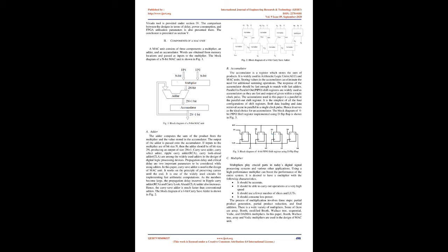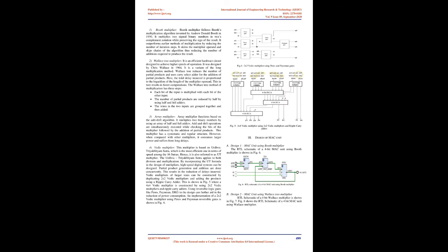In 4, a Radix 8 Booth multiplier has been designed for signed and unsigned numbers using Verilog. The multiplier has been implemented in a Spartan 3 kit. The Wallace tree multiplier has been designed, implemented, and analyzed in terms of speed and equipment cost in 5. The multiplier has adopted an algorithm which reduces the number of summands and accelerates the formation and addition of summands. In 6, the Wallace tree multiplier is compared with the array multiplier, and it is shown that the Wallace multiplier outperforms the latter in terms of speed and power consumption.